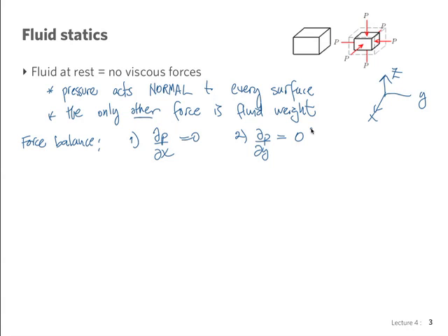Pressure basically is acting on every surface of this small little volume equally on all the vertical faces. It is only on the horizontal faces where we can see that there needs to be a change in the pressure between the top and the bottom face so that we could have something balancing out the weight.